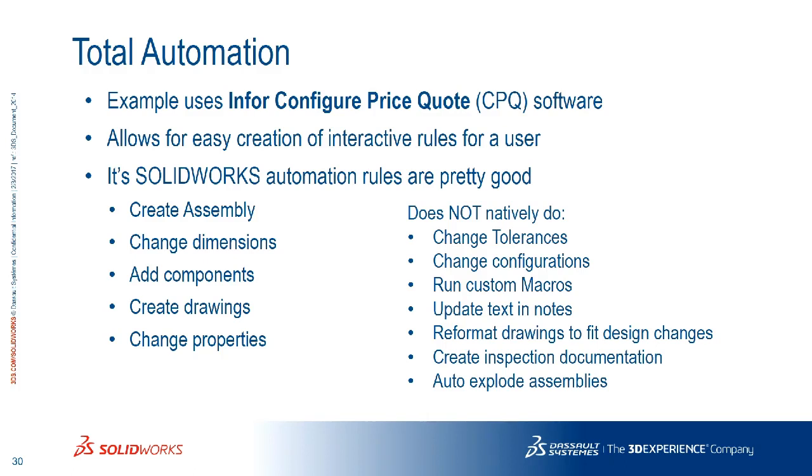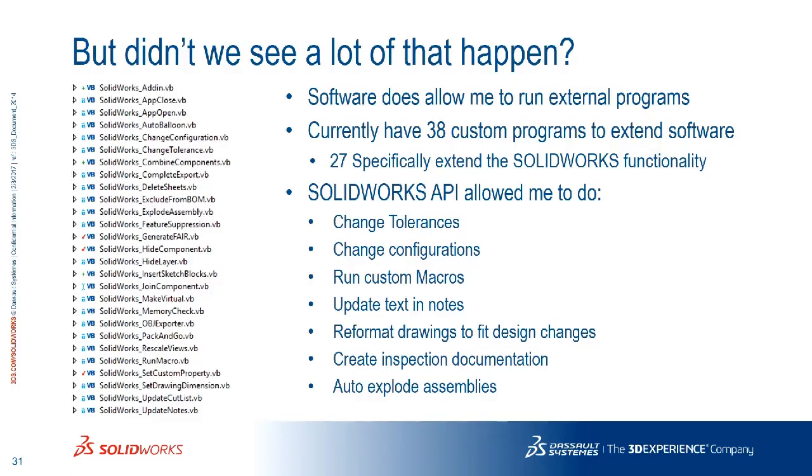It doesn't update the text in notes, doesn't auto-explode and auto-balloon things for me. But you might be thinking, well, we just saw all of that. But that's why I've been writing all these custom programs. I've got 27 specific programs for this that I've written using the SOLIDWORKS API to extend it to make it do exactly what a design engineer would do, what an engineer would need, all of the production information. That stuff doesn't come canned with a lot of these packages. You'll have to go through and extend them to get that functionality.